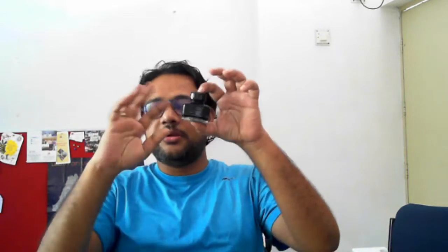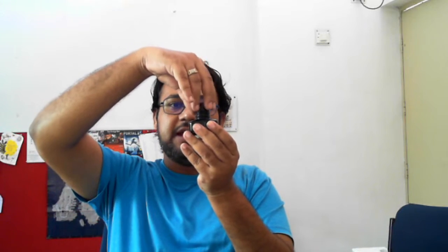And what you need to do is, let's say I chose this object. So this is a small object, right? So I want to make a casting diagram of this. And what you do is you take a look at all of this, you really analyze it. I want to make a casting diagram of just the bottle. So if there needs to be a cope or a drag, or if there is an undercut, then think about all of those things.